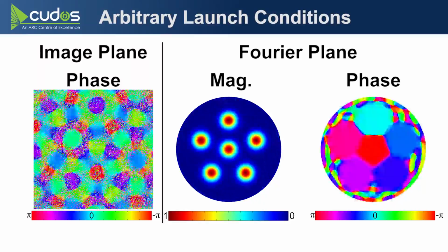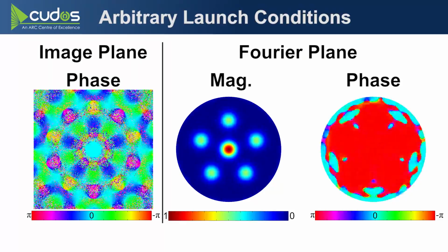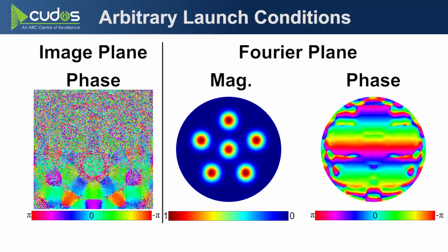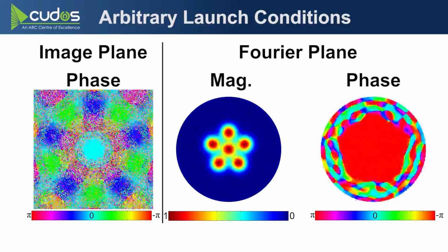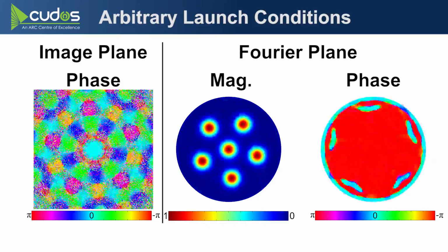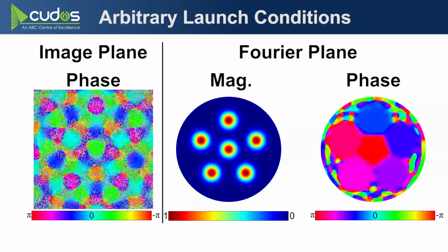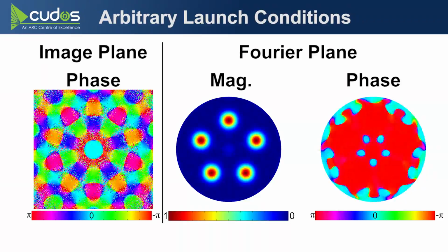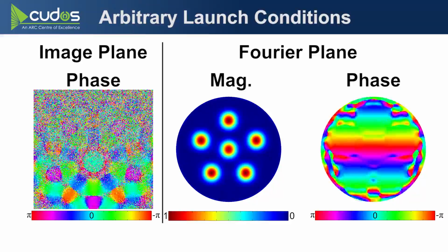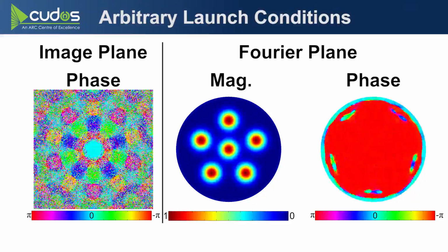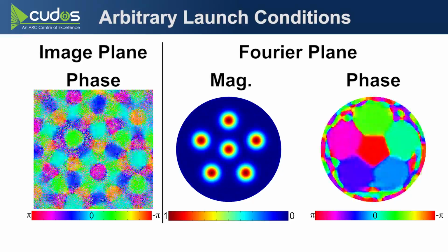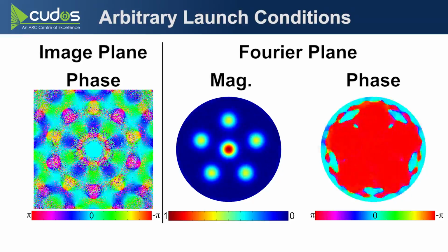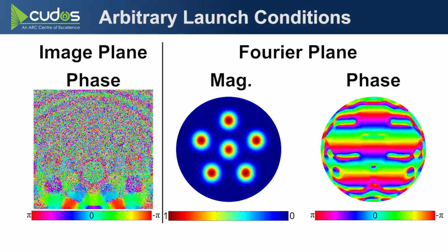Now if you're going to be doing a lot of 5-spot launches for a transmission experiment or something, then you're better off just doing it for real with an array of fibers. But if you're just looking to try something out quickly, then the SLM could be very productive, in the same way that you might use a WaveShaper in the lab to program an arbitrary optical filter rather than ordering a custom filter. You can try a lot out very quickly.